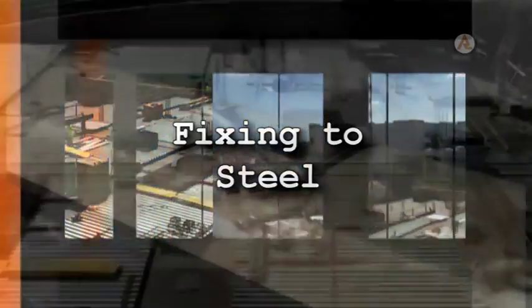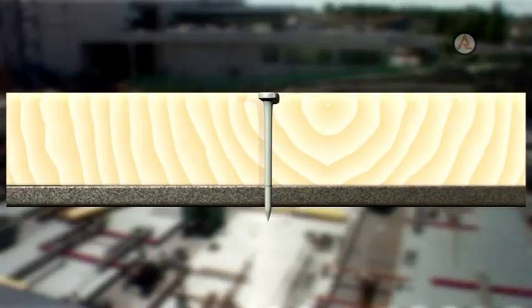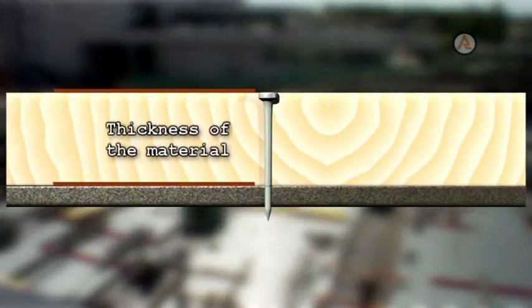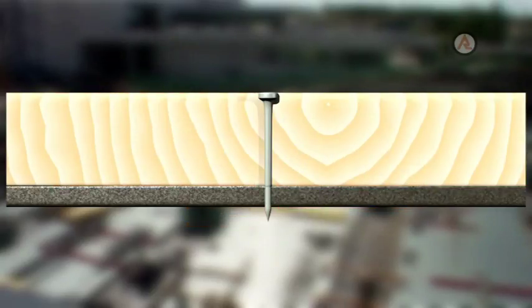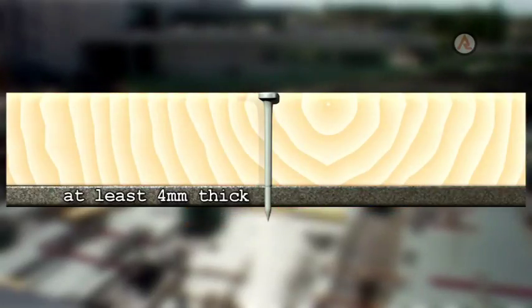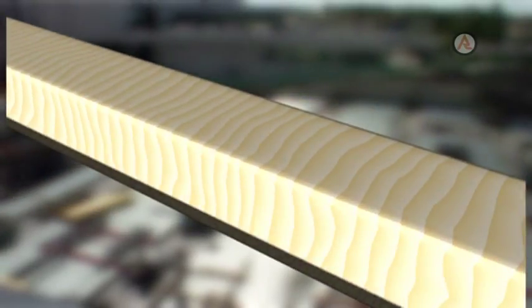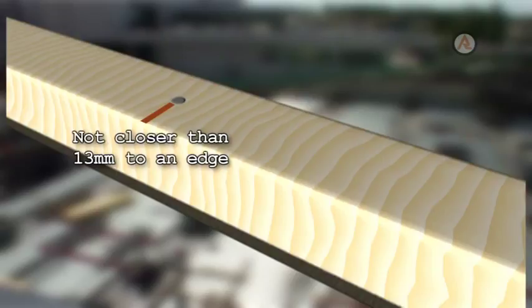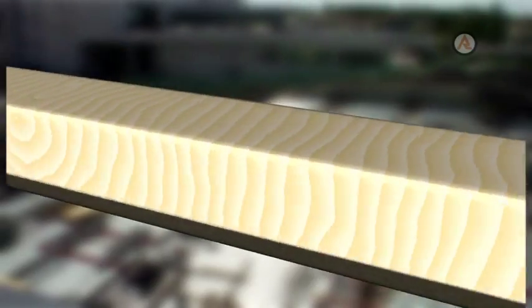Fixing to steel. When selecting a drive pin or stud, the overall shank length of the fastener should include the thickness of the material to be fastened, plus the thickness of the steel, plus 6 mm to ensure that the point of the fastener extends right through the materials. When fixing to steel, which must be at least 4 mm thick, fasteners should not be driven closer than 13 mm to an edge or closer than 25 mm to another fastener.